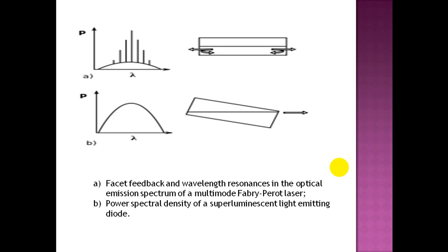SLEDs are designed to have high single pass amplification for the spontaneous emission generated along the waveguide, but unlike laser diodes, insufficient feedback to achieve lasing action. This is obtained very successfully through the joint action of a tilted waveguide and anti-reflection coated facets.